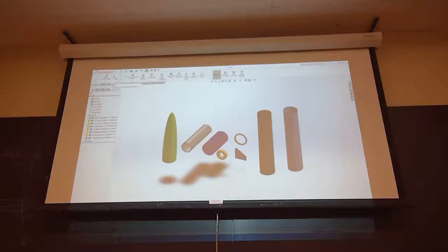Okay, so let's go ahead and hit mate. Now it'll show you this nice little panel where you can do a couple of things. The first box, highlighted blue, wants two things that you mate together, and that's pretty much all. You're only going to be able to enter two because it positions two components relative to one another. Then if you go lower, in this area you have your standard mates, which is all we will be using for today.